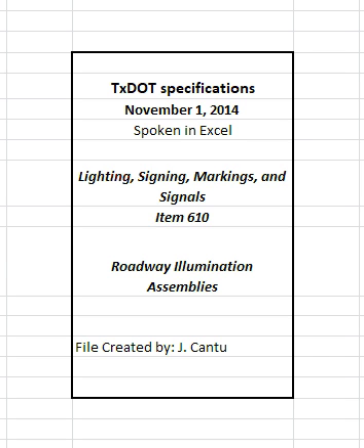Fabrication plants that produce roadway illumination poles, including luminaire arms, must be approved in accordance with DMS 7380, Steel Non-Bridge Member Fabrication Plant Qualification. This includes fabricators of aluminum roadway illumination poles and luminaire arms. The Construction Division maintains a list of approved fabrication plants of roadway illumination poles. Furnish light fixtures from new materials that are in accordance with DMS 11010, roadway illumination light fixtures. Provide pre-qualified light fixtures from the department's MPL.